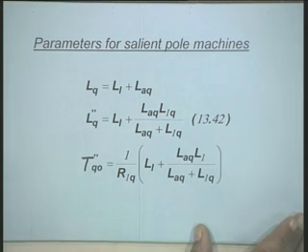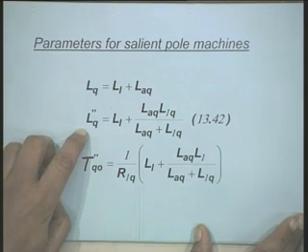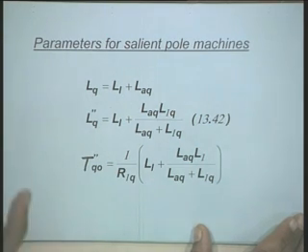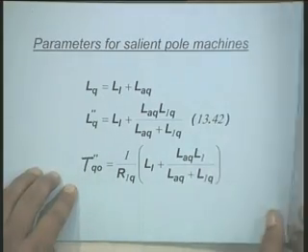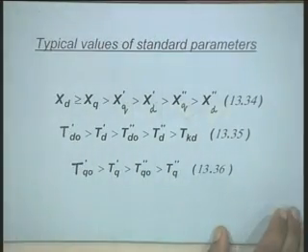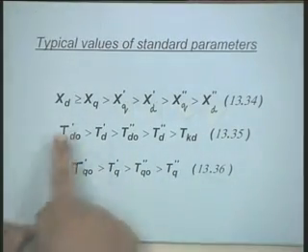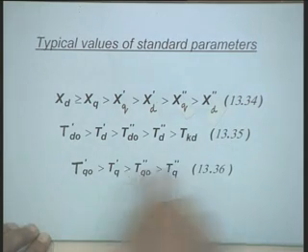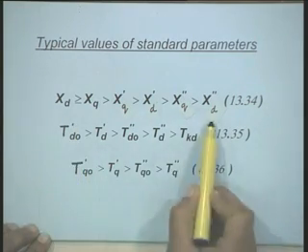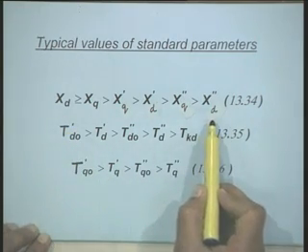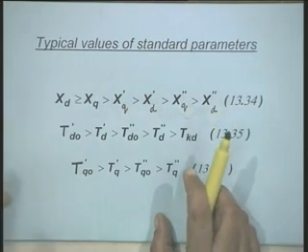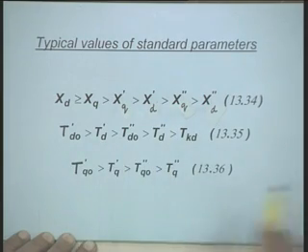There is no mention of transient, we always call it subtransient, okay, because we are considering one damper winding only. These are the expressions for salient pole machine. Further, you will see in the literature, or this discussion will show you, that these are the relationships between the different types of reactances, because in the per unit system the inductance is the same as the reactance, okay. These are the standard relations which are given.